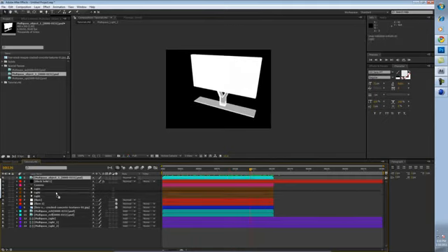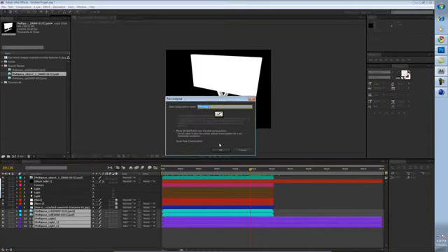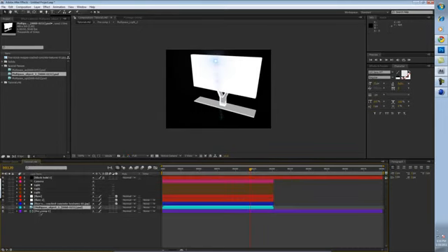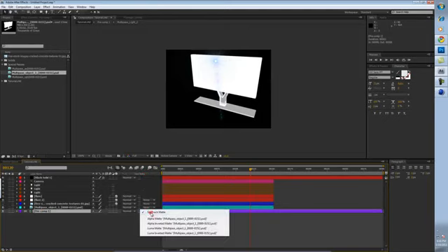Now, what I can use this for is I can take all my lights and reflections and put them in one pre-comp, and take the pre-comp and use the track mat function and say track mat luma mat multipass object 1.